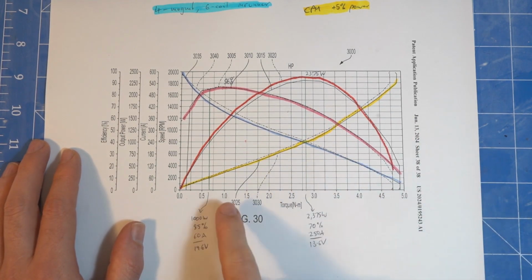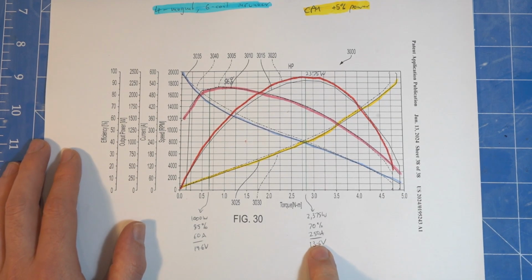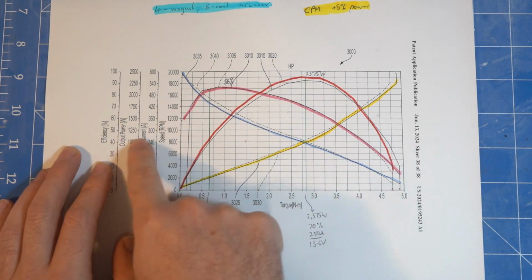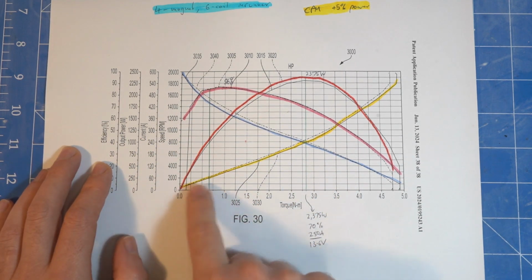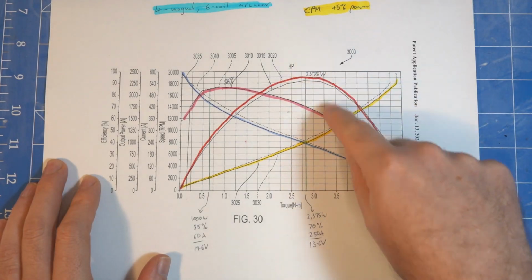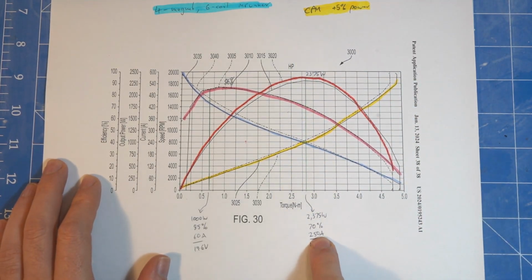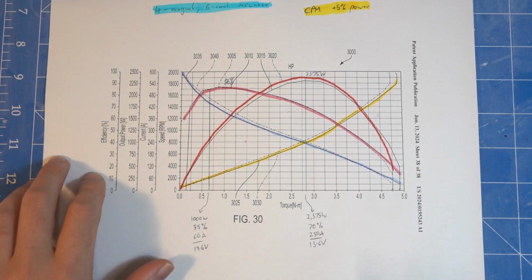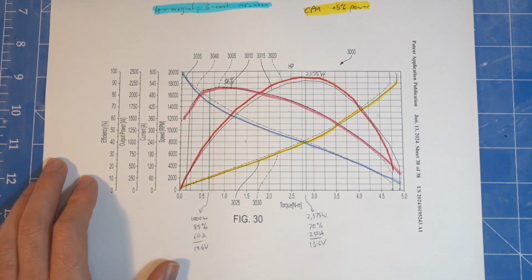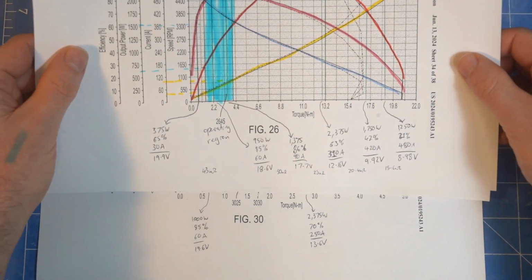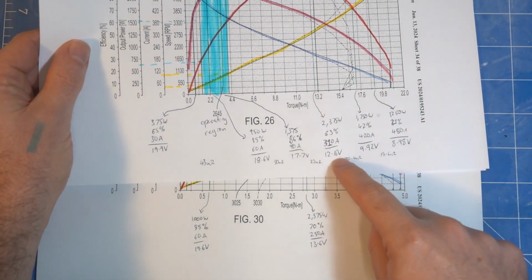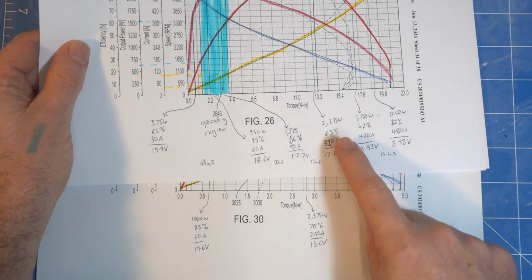But this one, from the calculations, is 18 volt, although with quite a big voltage sag here, down to 13.6 volts, 250 amps, nothing wrong with that. Yeah, 86%, 1000 watts, and 60 amps. 2375, 70% efficiency, and 250 amps. So I'm pretty sure Milwaukee is not going to let you drive this motor that hard. Here's our other one. 310 amps, 12.6 volts. Yeah, they might be using the same battery pack for that.